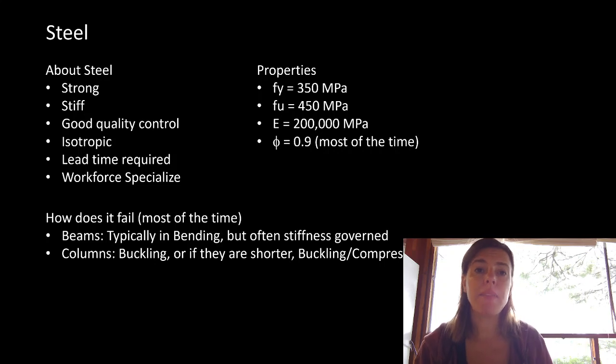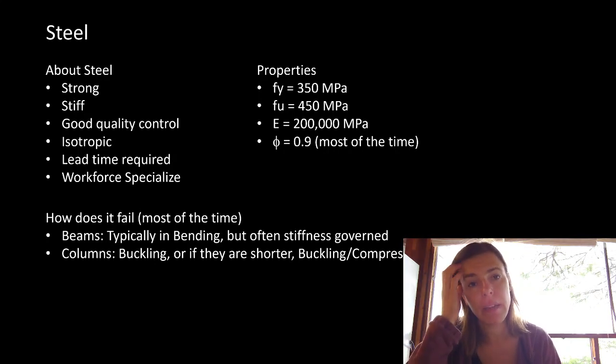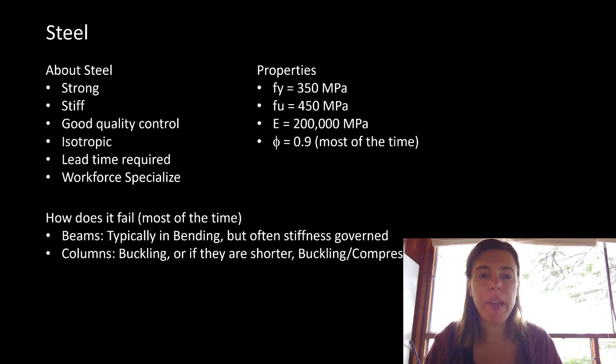The properties of it. It yields at 350 MPa. Remember, yield doesn't mean permanent failure or a complete failure. Yielding means that we will undergo permanent deformation. We tend to like to keep things in the elastic zone on our stress strain curve, which means any load we apply that causes internal deformation of the system, when we take the load off, goes back to normal.